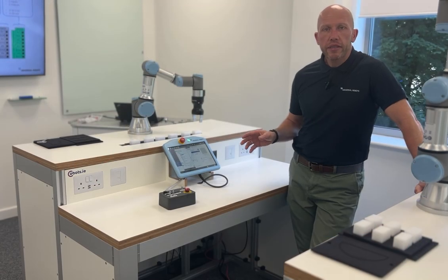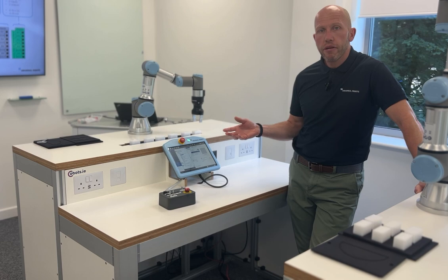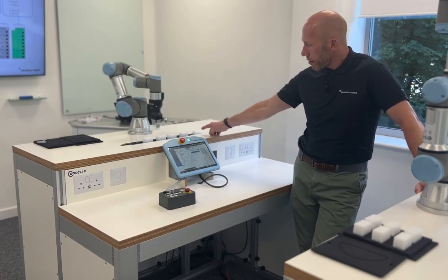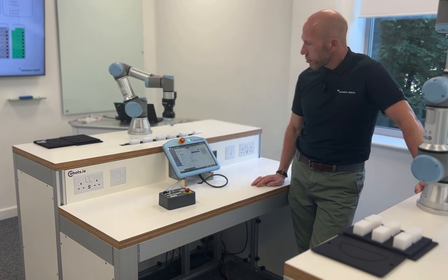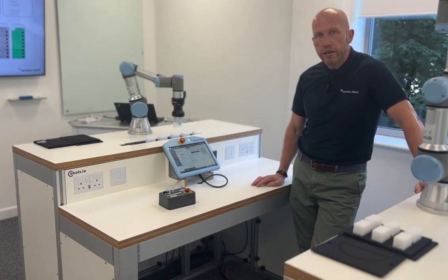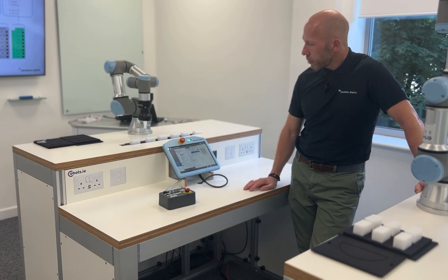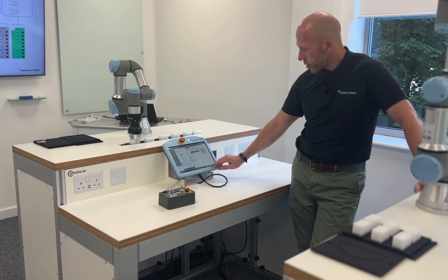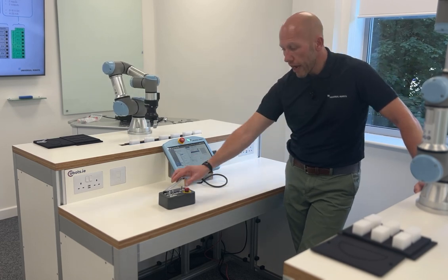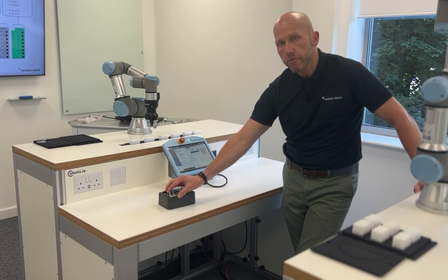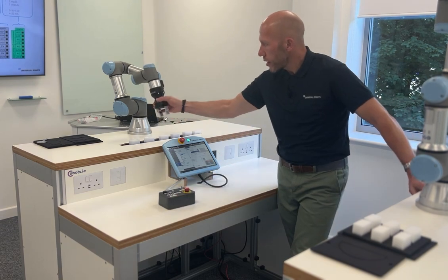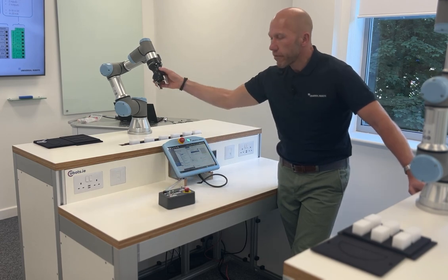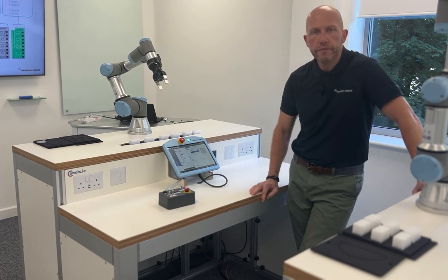Okay, now we've interfaced those signals and we've renamed them. We can play the program and see how that interacts. We've got conveyor out feed, conveyor in feed. The robot's controlling the conveyor via a thread, so it moves to and fro. Then if we stop the robot, I will use digital input 0, which is my free drive. Click that, and now the robot's in free drive. You can take it out of free drive, and now the robot's not in free drive.